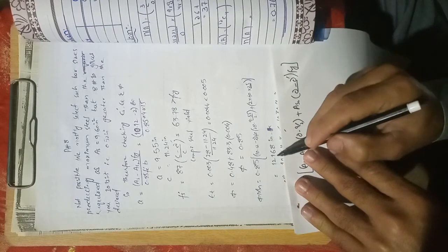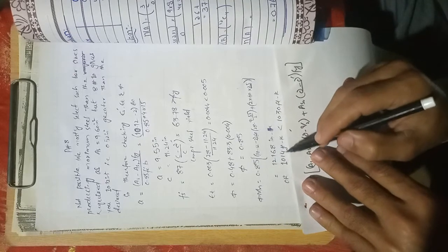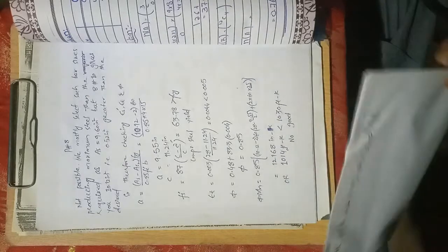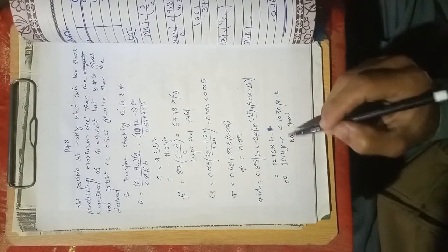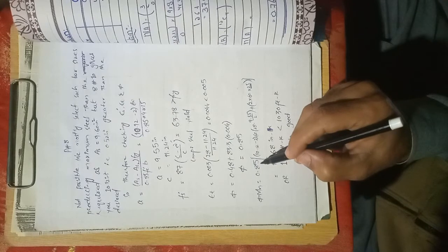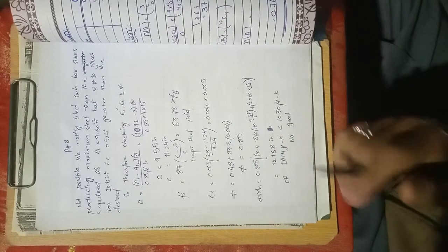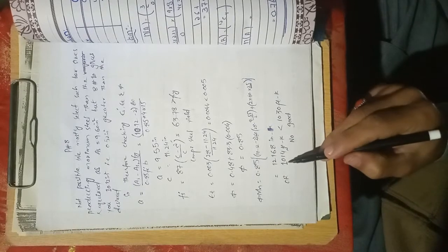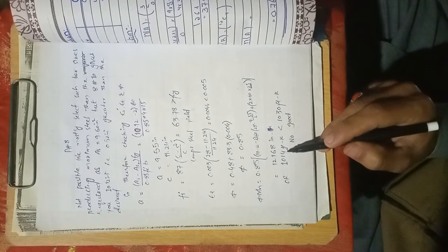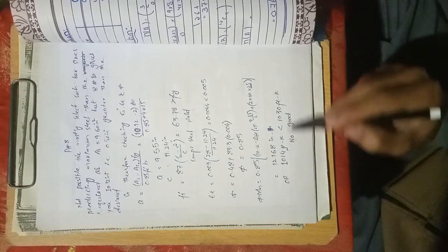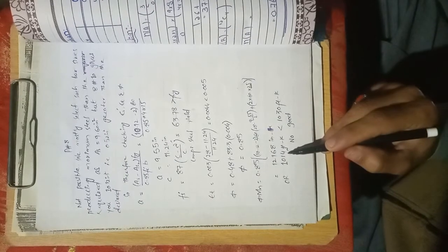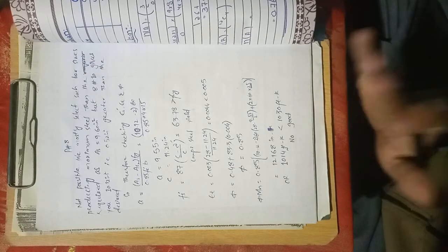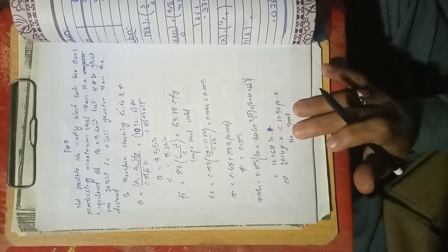This is important. 12168 inch-kip, right? Dividing it by 12, we got 1014 feet-kip, which is less than 1030. This is important. Now you see the effect of the phi value. Because we reduced the value of phi, it will further reduce the moment capacity of the section to 1014. Here, if you see, we are close to the desired moment capacity. Although the design is okay and will work, all right, but